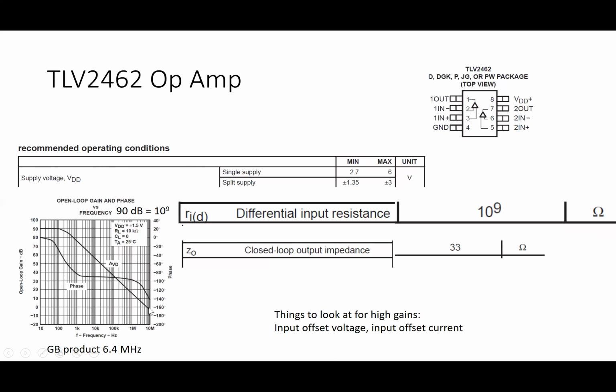This doesn't matter very much if you're using the chip at unity gain or a gain of a few. So here's 20 decibels, which would be 10 squared, or a gain of 100. So you could do that without worrying too much. But you'll see that, in fact, as you increase the gain that you use, you'll want to limit the upper frequency that you use the chip at.